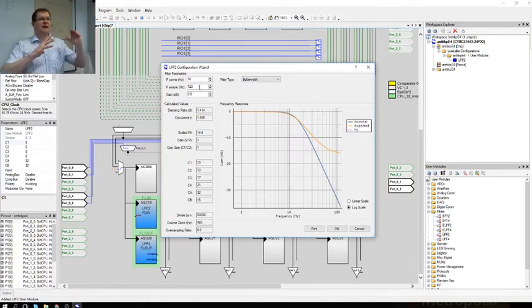Why am I using that much of the low pass filtering? Well, remember that our final sampling rate will be 2 times a second, which means the sampling rate for the final result was 2 Hertz.